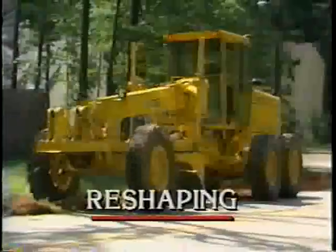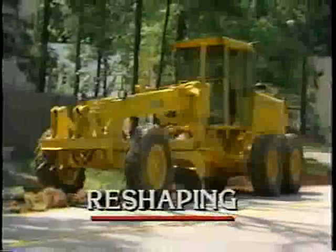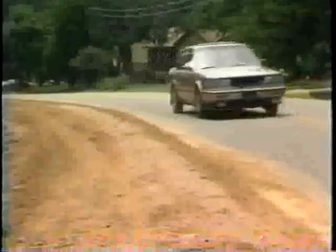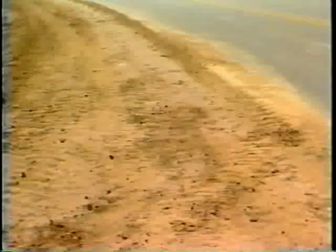The first type of shoulder maintenance is reshaping of the shoulder. No additional shoulder material is added, and no excess shoulder material is removed. Reshaping restores the desired cross-section and slope of the shoulder. The end result is a smooth shoulder with a smooth transition from the edge of pavement sloping down to the front slope of the ditch.